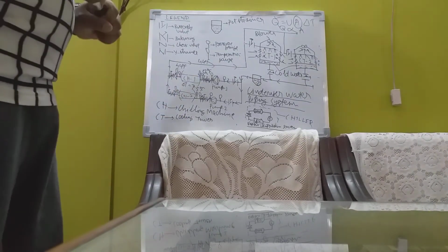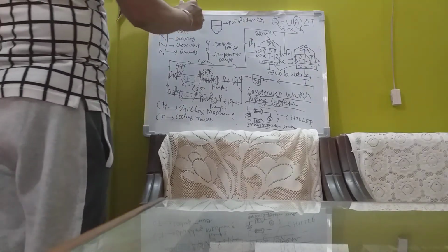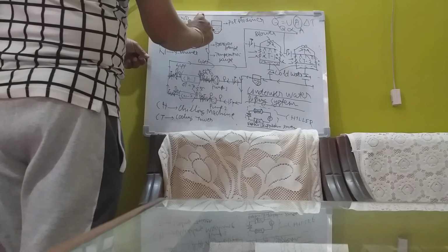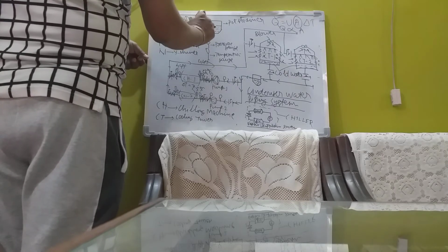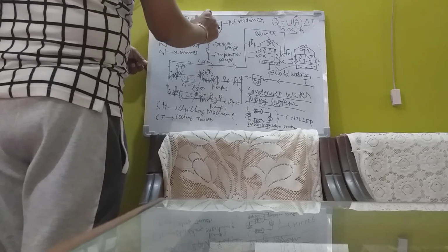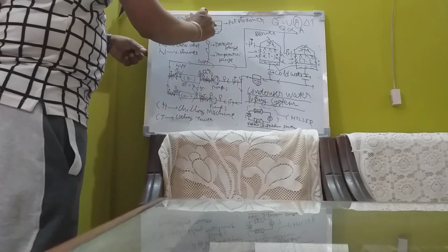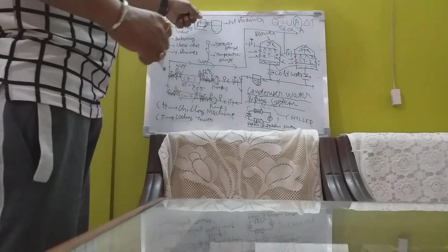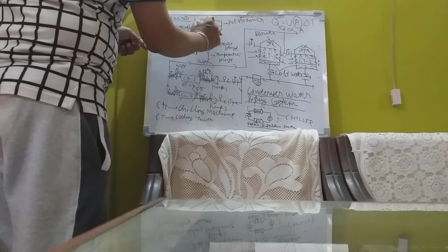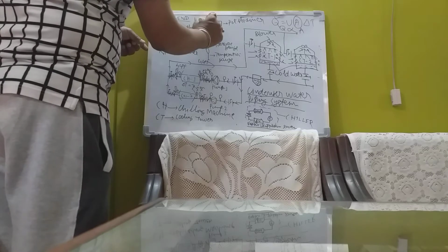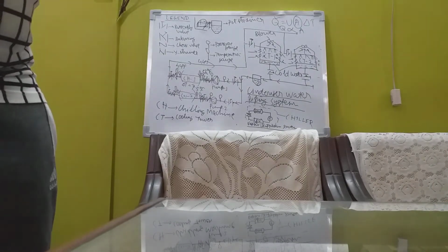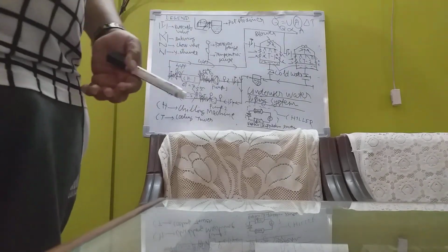The temperature of condenser increases means, if you take the pH chart, this is the pH chart, and you find this condenser temperature increases, as you read in the last semester, 7th semester. As a result of that, the compressor work increases. Compressor work was earlier this much, now compressor work has become this to this. Earlier it was this to this. Compressor work more means electric power consumption is more. The electric bill is more.